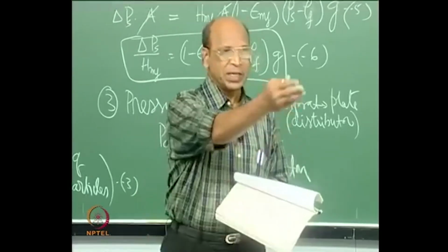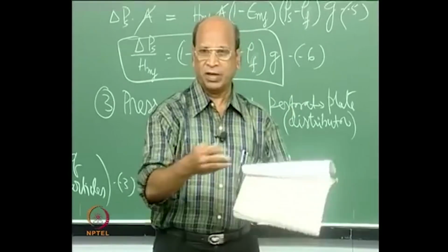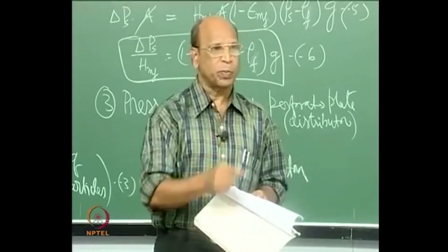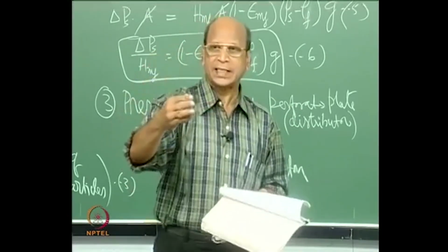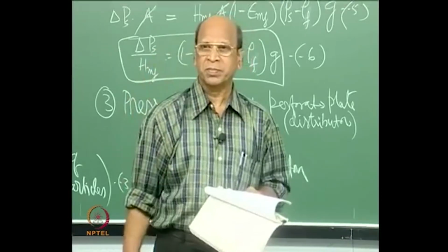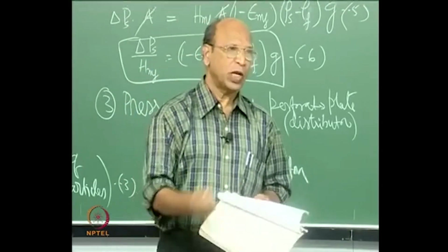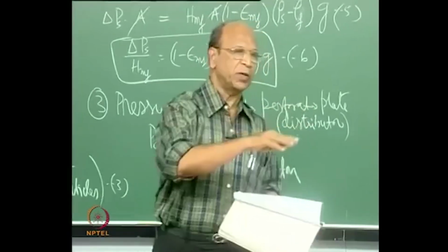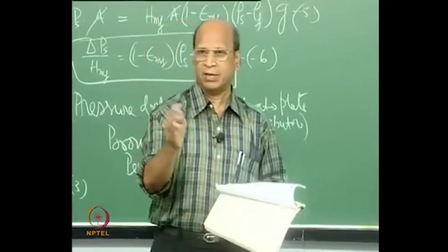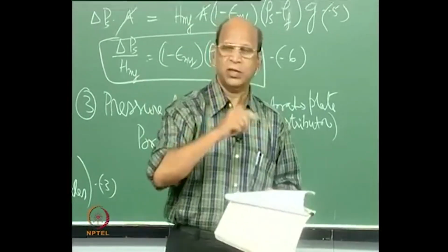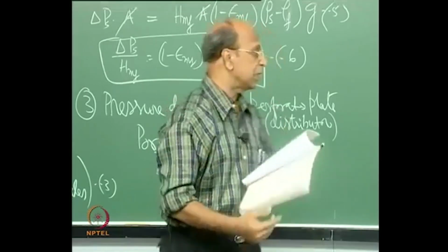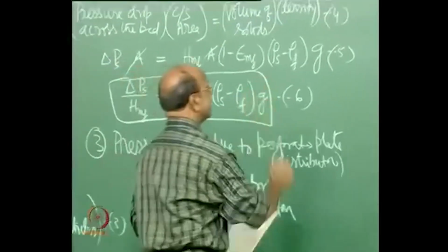Okay. So, the same thing even for heat exchangers, but that is not good, because when you talk about cleaning, square pitch is better, because you will have at least some more space in between. So, where you can clean it, and then once in a while you have to clean it, otherwise it will be fouling and all that. So, heat exchange may not be there after some time. So, this is the general thumb rule.